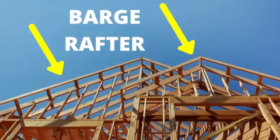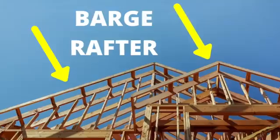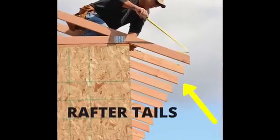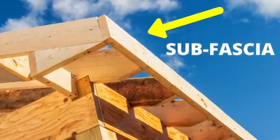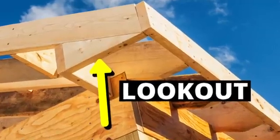On gable roofs with an overhang or an eaves, the suspended rafter hanging out in the open air is called the barge rafter. Down at the lower point, the projecting end of the rafter is called a rafter tail. These are usually tied together with a subfascia. And in houses that will have an enclosed soffit, the little backstrap piece of framing is sometimes called the lookout.